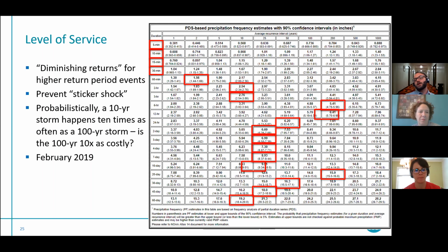Because as you see, as we get out to 20 days, there was another reasonably large storm somewhere between 10 and 20 days that put them back up to a 200-year recurrence interval in a single month. They had almost 16 inches of rain in February of 2019. And that's hard to plan for, but if you'd only looked at the 24-hour, you may not get the whole picture of what the intensity was, and thus what the impacts